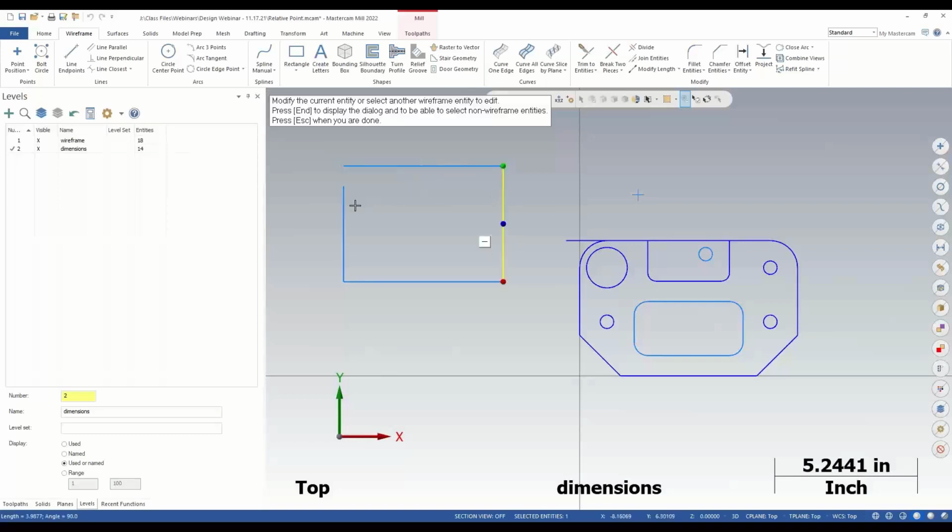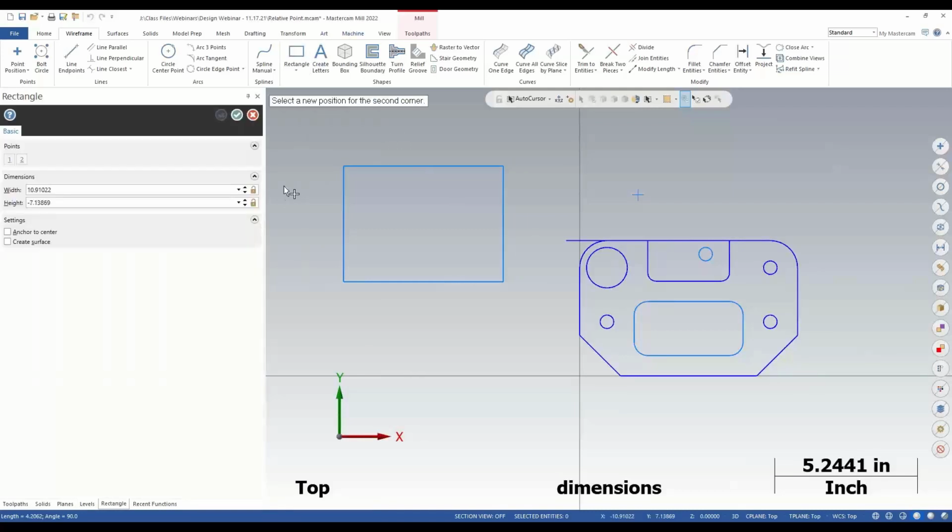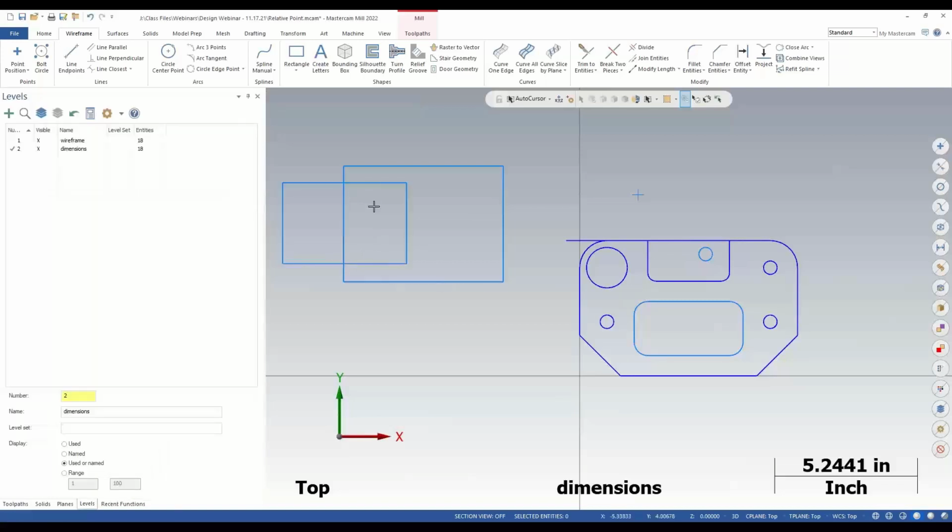I can only do this with one line at a time, and then I have to, yeah, you come through here and pick join the other entities too, or something like that. Okay. Yeah, you have to do join or move it like that. So unfortunately, we still can't grab a rectangle after you've created a rectangle. Of course, if we were in the rectangle tool, we can still adjust the width and the height in here, but not in the case after you green check out of here, because these become 4 lines at that point and they become completely independent from each other.